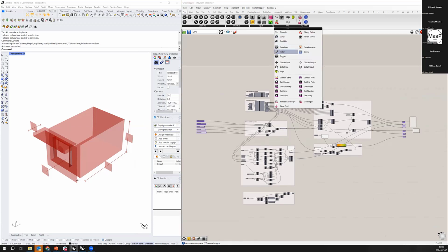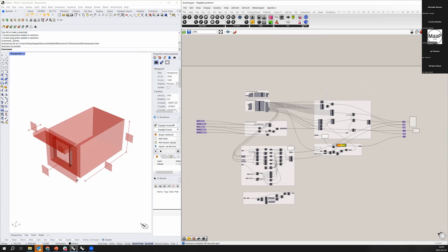So once you upload this Grasshopper script to Rhino.Compute, the way to get inputs and produce outputs to interact with anything outside of Rhino.Compute are these components here, if someone has never used Rhino.Compute. So you get these get components that are used for the input, anything from geometry to integers or strings. And then you have these 2 on top, context bake and context print, which are the ones used to produce output and send something from Rhino.Compute somewhere else. The context bake is used for geometry, anything that is geometrical output, and the print is used for anything that is more like a string or numbers or this type of data. So it's just a little bit to show.